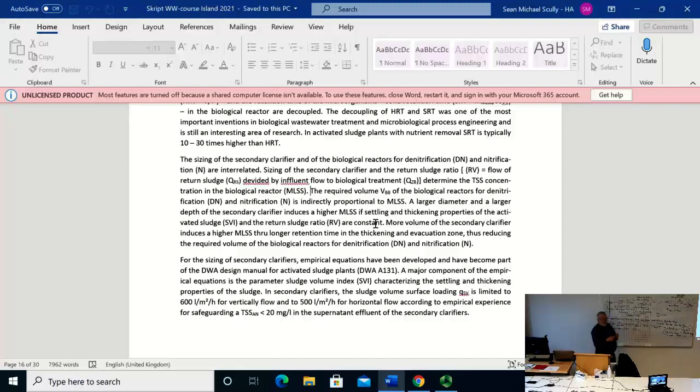When the sludge volume is very high, all the flocs stand upon each other, and there's hardly any sinking and no compression anymore, and reduction of the sludge volume. So normally it doesn't make any sense to make it much larger.